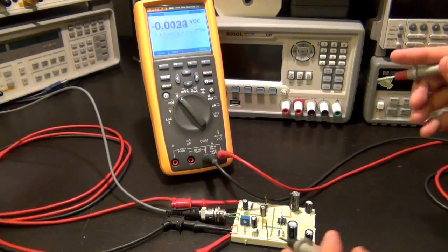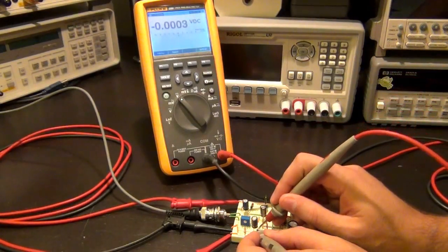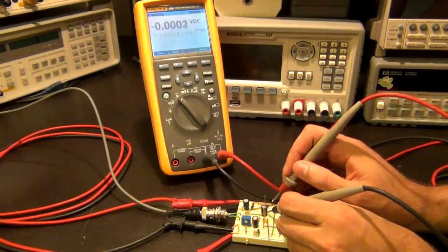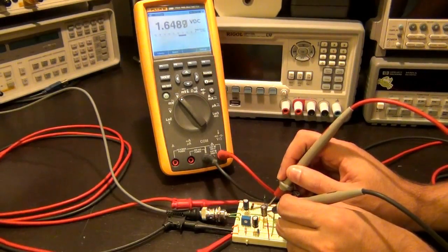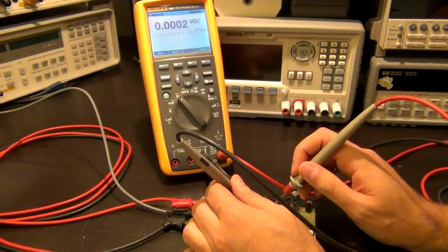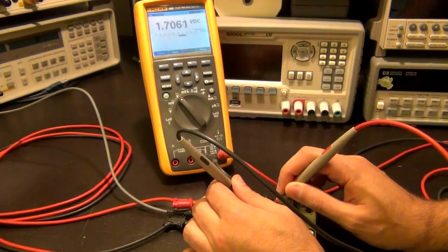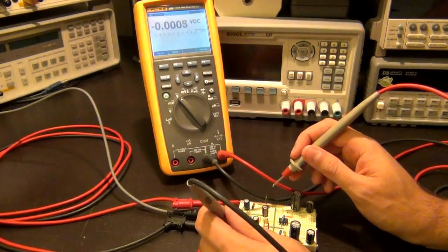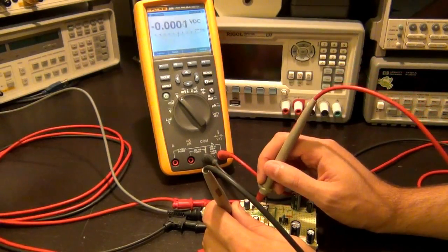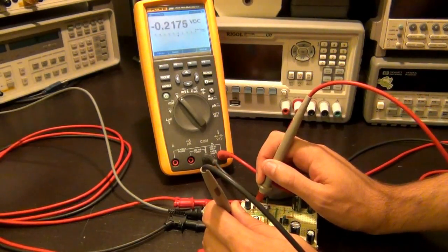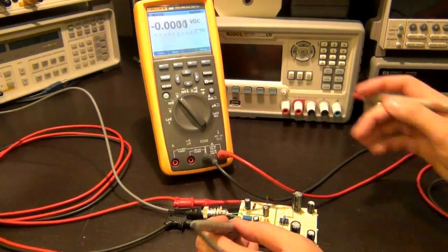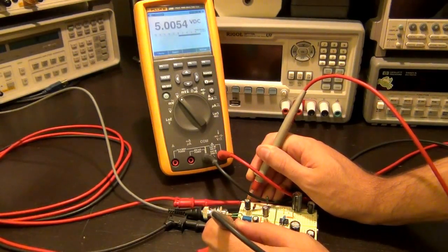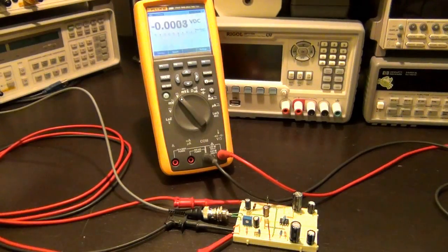So let's measure that. I'm going to measure the voltage across the emitter resistance. There you go, 1.64. We designed for 1.6. It's pretty good. The voltage across the collector resistor, again 1.64, no problem. The voltage across the collector-emitter of the device, 1.7 volts. We designed for 1.8. It's close enough. And the voltage on the base of the device itself, which is here, base voltage is minus 0.2 volts. It should be about minus 0.3, but it's pretty close. And of course my plus and minus 2.5 volt supplies should be correct. There you go, that's plus 5 volts between the two power supplies. So everything checks out. The DC operating point of the amplifier is actually correct.